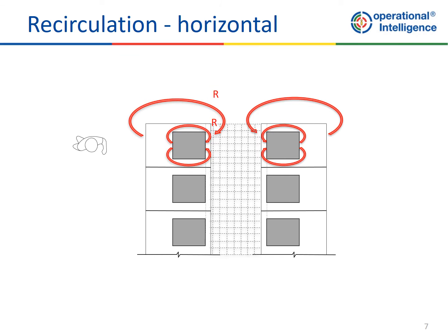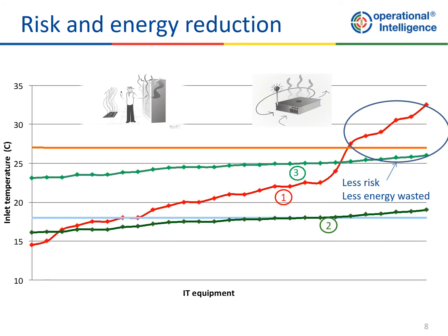So if you look inside the rack, on the side of the server, you'll see hot air coming back, particularly if there are no brushes or no Correx to blanket off. And particularly on the last rack of a row of racks like this one, you can notice it externally to the rack. And you just put your hand here and you see the hot air coming back this way. So just by using your hand, you can get a sense of if you do actually have bypass and recirculation. It's a pretty good parameter actually.